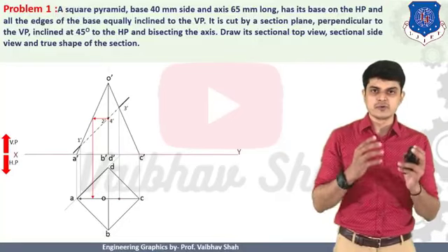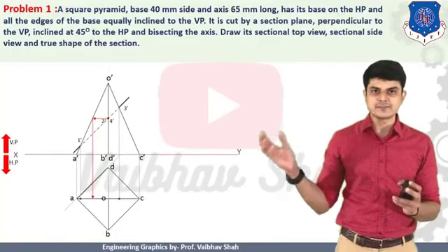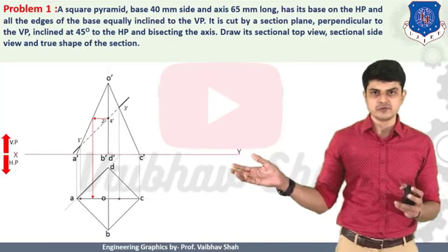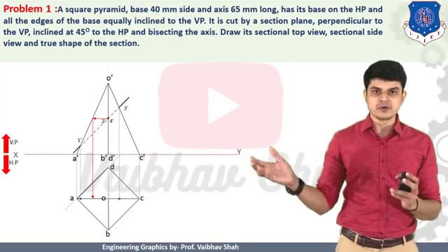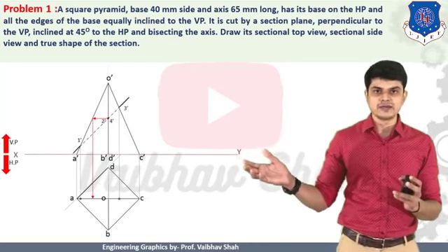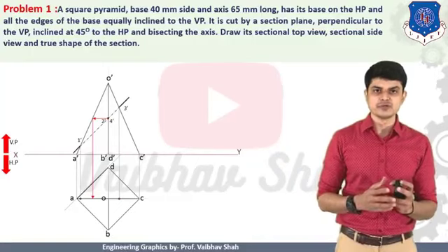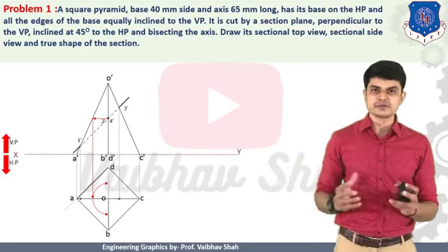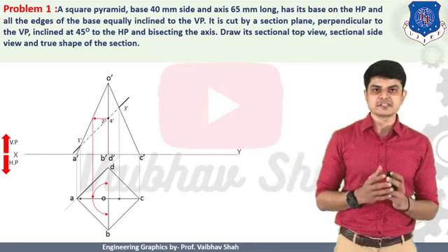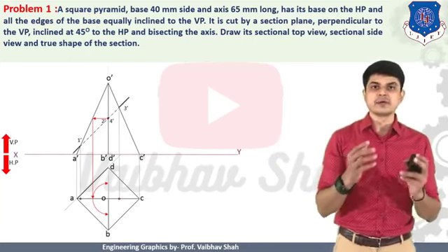So we should take our rounder. Take your rounder, then put it at the center point O in the top view. Then take the radius equal to center point O till your red arrow on your OA line in the top view. By keeping that radius in your rounder, you should draw two arcs like this. So you will have two points transferred onto your OB and OD lines respectively. Now your point is finally transferred to your OB and OD lines.